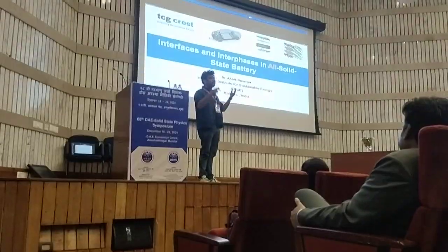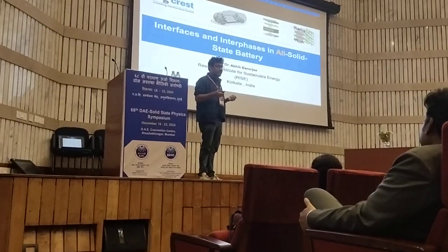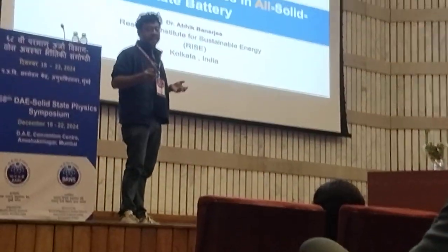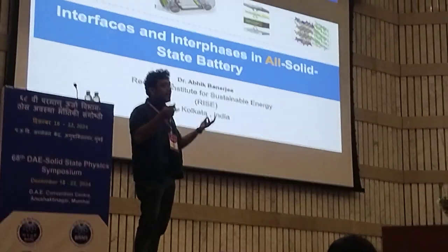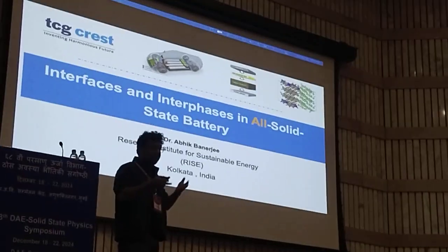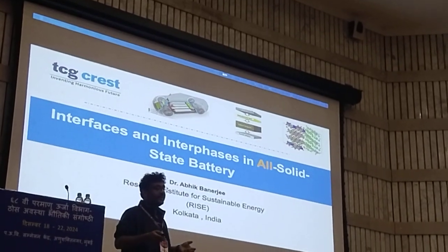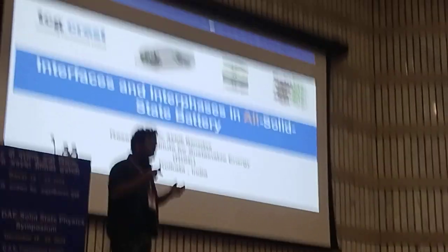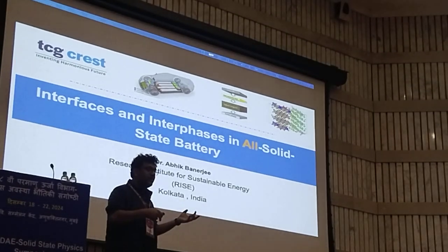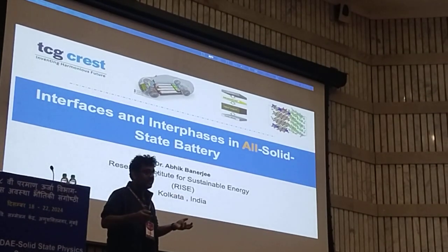Battery. But the concept of all-solid-state batteries is that there should not be any kind of liquid electrolyte at all. And the interface is more complex. You can just imagine that a liquid can infiltrate and wet all the surfaces, but a solid is not a fluid, right? It doesn't have the fluid nature. So how you create the interface from the very beginning when you make a battery is extremely important for solid state batteries.